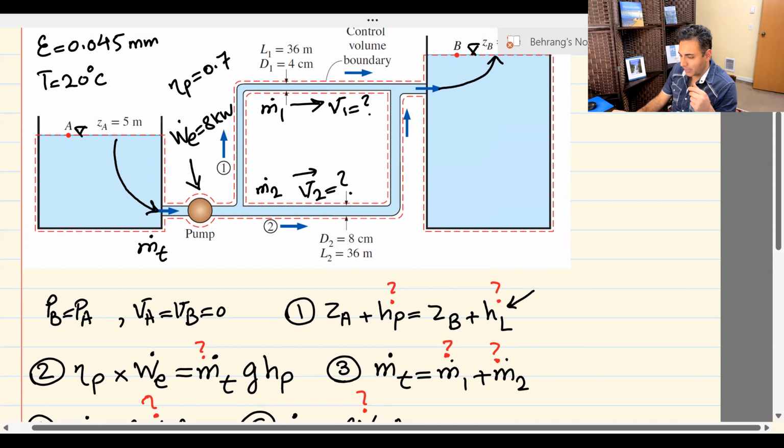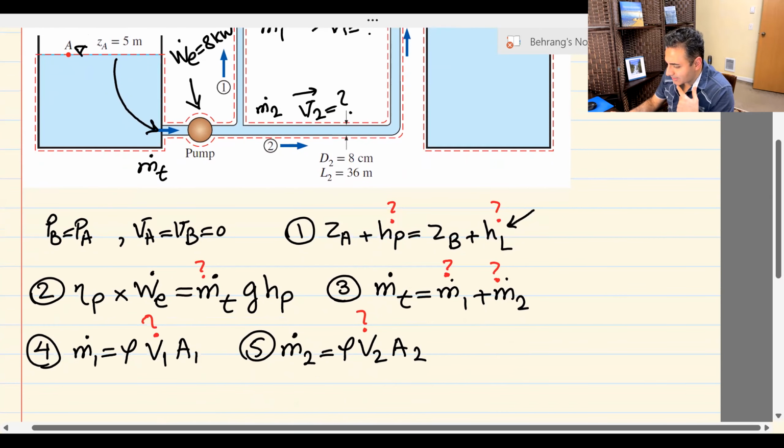That's one of the magics in fluid mechanics, that once we reach steady state, the laws of fluid dynamics will adjust the flow rate such that the amount of head loss in every branch that is parallel to each other becomes the same. So there's only one head loss from point 1 to point 2, which is the same head loss that showed up between point A and point B, right? And that head loss is the same in every branch.